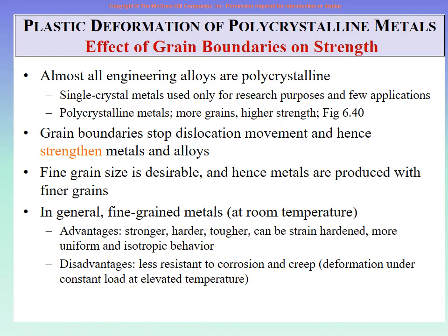We have shown you that some are BCC, body-centered cubic, some are FCC, face-centered cubic. Those are special shapes, and those metals have crystals of only that special geometry. But crystals are small shapes, so they are touching each other, and where they touch, that area is the grain boundary.